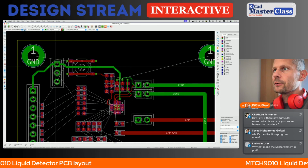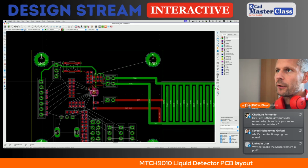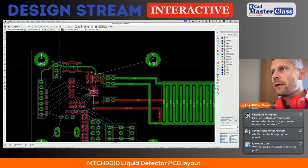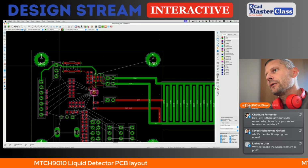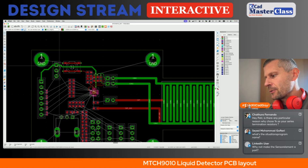Okay, so the 3.3 voltage is going from the system connector through the configuration jumper pin header. Is it okay or not?